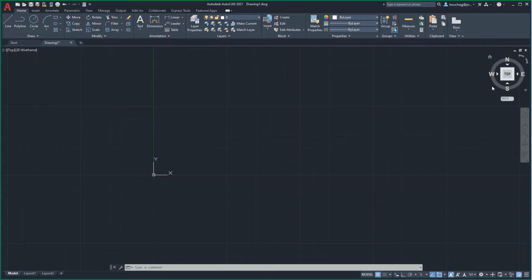As in all drawing and drafting environments, the top view is equivalent to the user looking straight down from above, also known as the plan view. And as we move our cursor and touch the corners and edges of the view cube, we note that each corner or edge highlights in blue. Selecting the small blue highlighted square at the bottom left corner of the view cube reorientates our view to the southwest isometric view of our model drawing space.